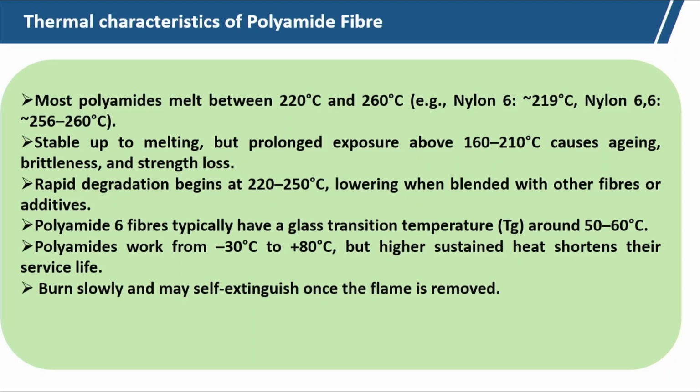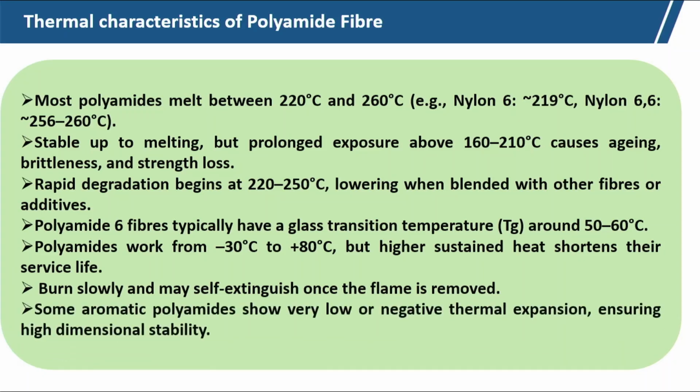They burn slowly and may self-extinguish once the flame is removed. So, they will not propagate the flame. Some aromatic polyamides show very low or negative thermal expansion, ensuring high dimensional stability. So, their thermal dimensional stability at high temperature is excellent, and they can be used at elevated temperature.